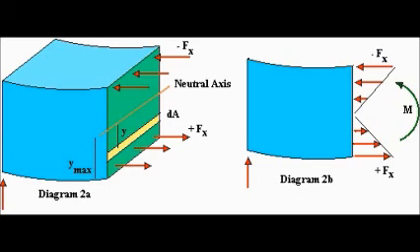When examining bending moment, horizontal forces act on the cross-sectional face of the beam section. We have shown only the horizontal forces along the top and bottom in the diagram at the left, but the forces act across the full cross-section as shown in the side view in the diagram at the right. The horizontal forces decrease from maximum at the outer edges to zero at the neutral axis.